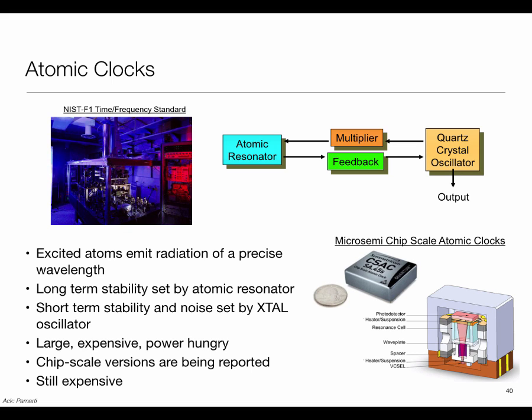It consumes around 100 milliwatt, 75 milliwatt, something in that range. So it's still power hungry. I mean, a lot of our embedded systems are in single-digit milliwatts, so this is certainly an order of magnitude more. But on the other hand, for many other applications, this is great. $1,500, pretty expensive. Again, you're not going to put it into a $1 sensor, but for a lot of other products, it's very good.